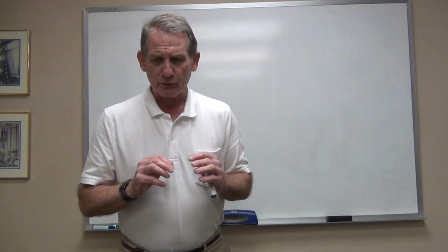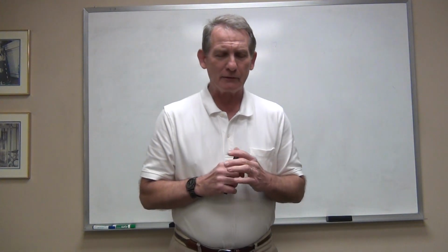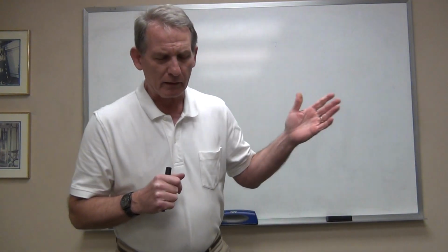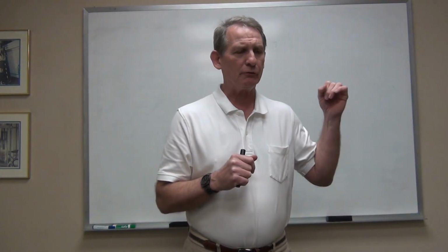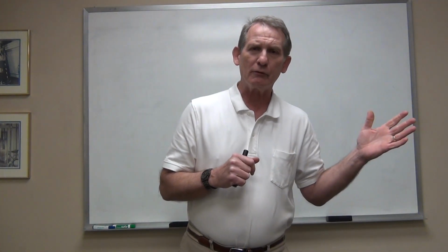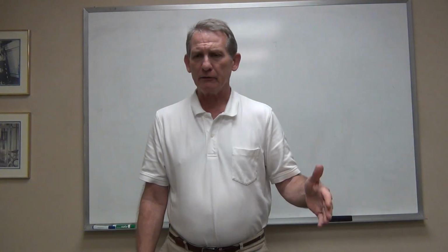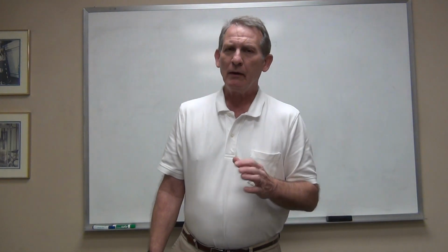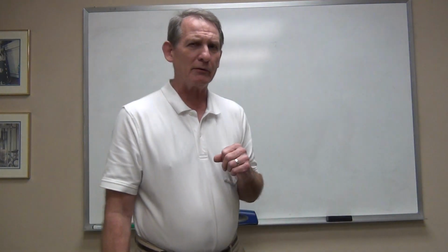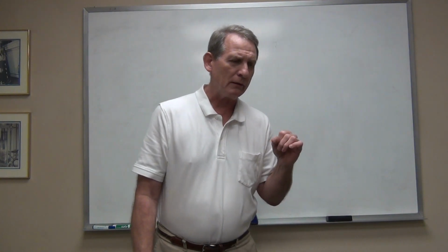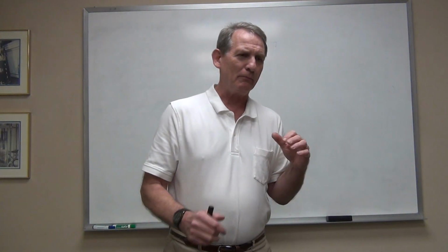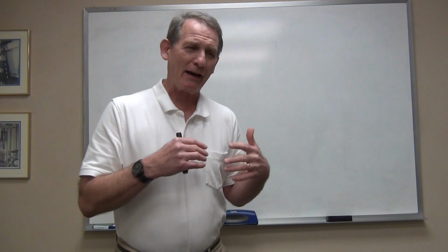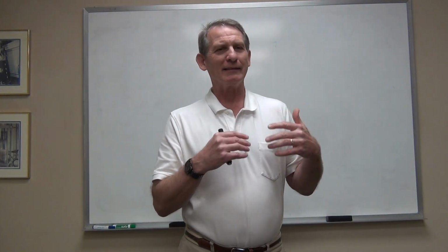Okay, so tolerances of form, we saw the concepts of line elements and derived median elements. We saw the effects of material condition modifiers and how they can adjust the tolerance zone based on the actual size of a feature. I don't think I mentioned it in the previous video, but you'll often hear that material condition modifier called bonus tolerance. And I don't really care for that term, but in a sense it sort of is.